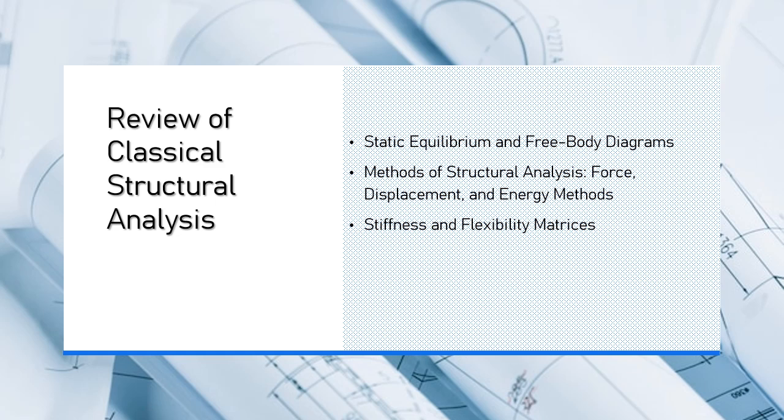2.1. Force methods. Force methods are used to solve statically indeterminate structures by calculating unknown forces, reactions, or internal forces directly. These methods are based on the assumption that the number of unknown forces exceeds the number of static equilibrium equations available, so additional equations are required to solve the system. The general process for force methods involves selecting redundant variables.